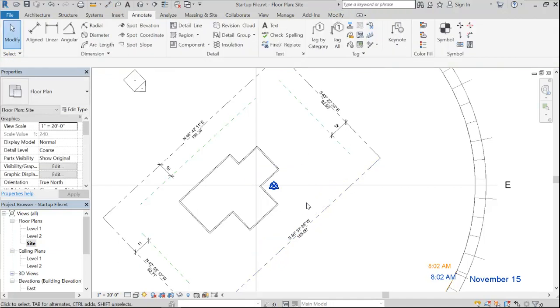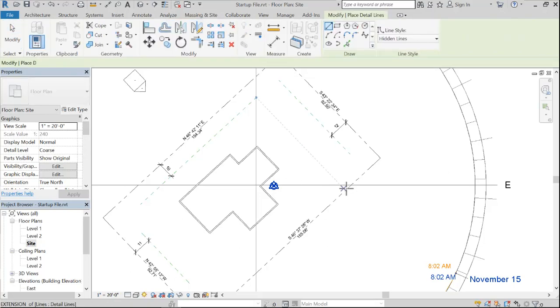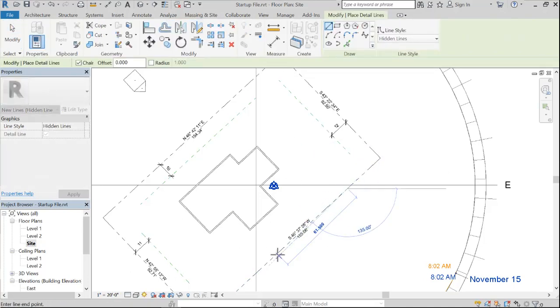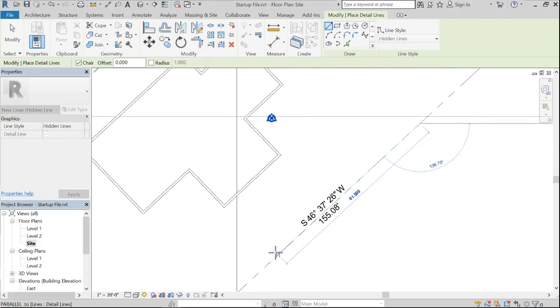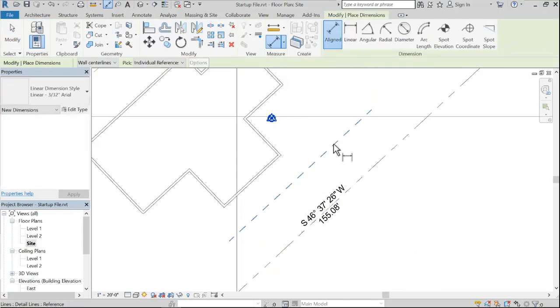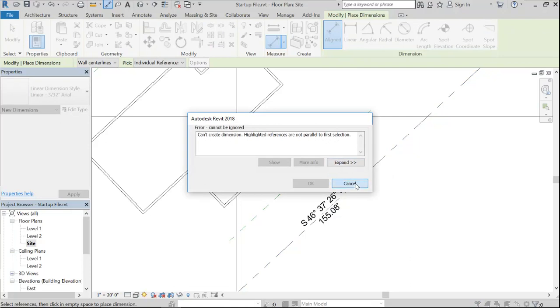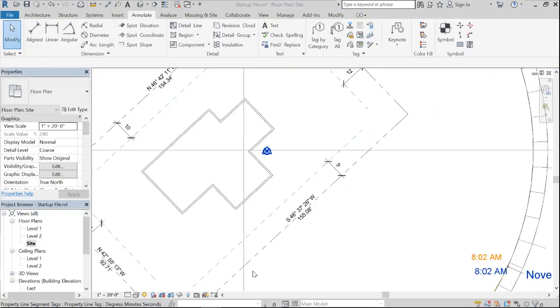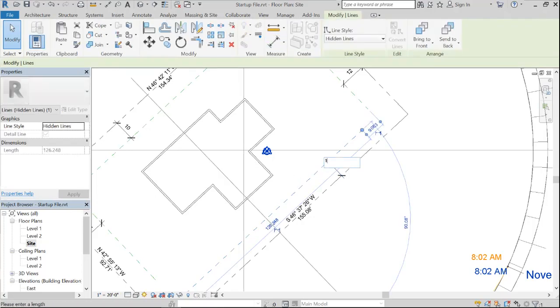And again, I have another problem with that line, so I'll draw that one on there again. It's giving me perpendicular, so now I have parallel. Pick that up, move it, add my aligned dimension on there. So I redrew that line, made sure that it was parallel. I click on the line and I change this to 10.